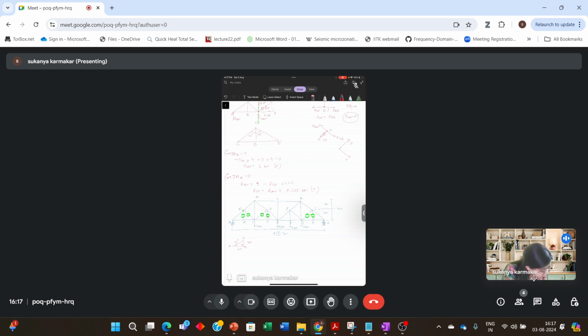So this has to be 90 degree. From there, it was seen that these angles which I just marked are 90 degree. Then again, this is a zero force member because at this point L, the forces in LM and LK will be equal in magnitude and opposite, and this will be a zero force member. So these are the zero force members in the truss.